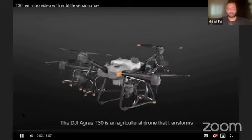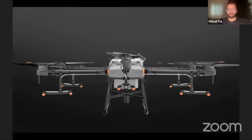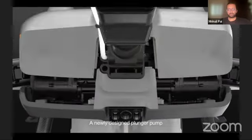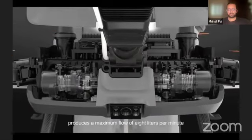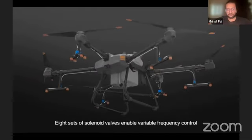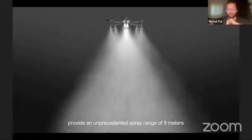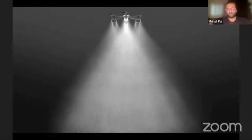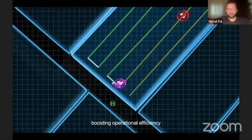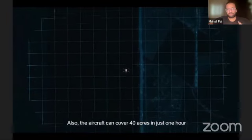Agras T30 is an agricultural drone that transforms. Take a look. The aircraft has a maximum capacity of 30 liters. A newly designed plunger pump produces a maximum flow of 8 liters per minute. 8 sets of solenoid valves enable variable frequency control, and 16 nozzles provide an unprecedented spray range of 9 meters. A new smart gauge indicates the estimated time until refill, boosting operational efficiency. Also, the aircraft can cover 40 acres in just 1 hour.